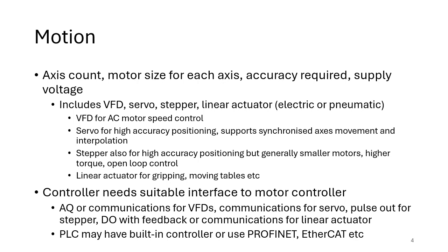Variable frequency drive gives you support for AC motor speed control, but is otherwise relatively slow and inaccurate. But VFDs can be useful, particularly for larger motors, because they can improve efficiency overall, and that can reduce the overall cost of investment and the return on investment. So you might be paying more upfront, but the overall energy cost can be reduced, and that can reduce the cost of the system over time.